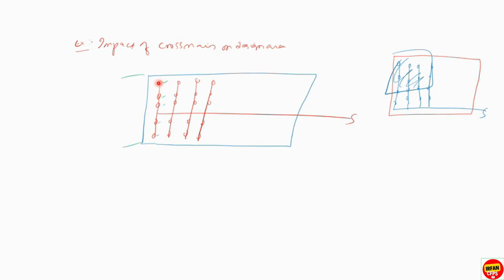When you select the design area, you need to make sure to select the highest pressure as well as the highest flow demand sprinkler. This is the highest pressure demand, but the highest flow demand will be this one, not this one, because I will just write it down here.